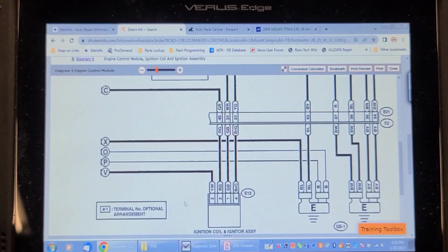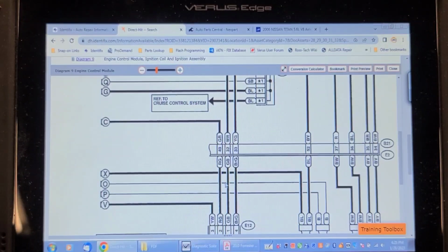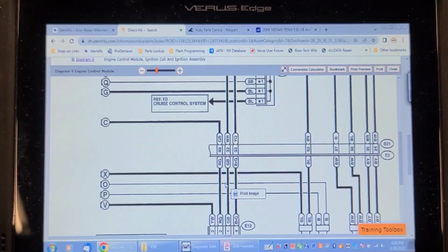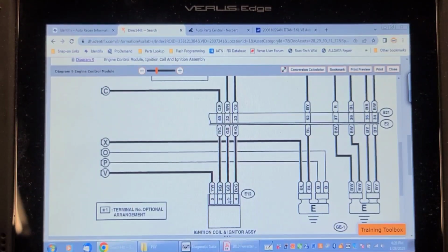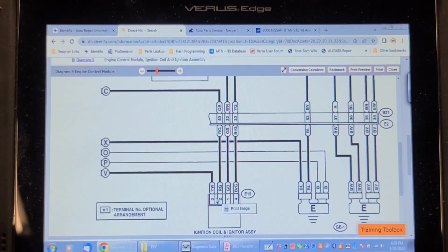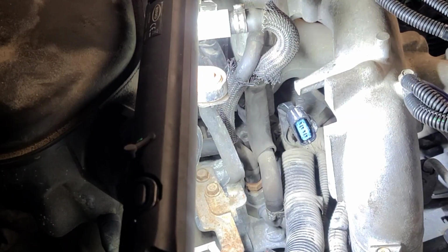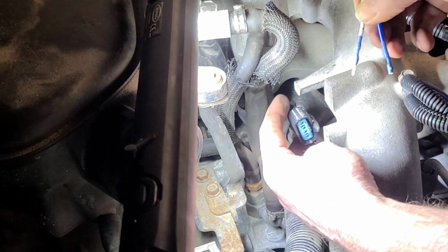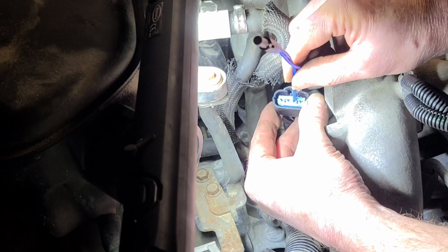I decided to take the coil off and put 4 jumper wires in across the coil, and check pin 1, which is the green wire. And I think I may have found something of concern when I was inserting the probes in there. Pins 2 and 3 are the power and ground. I'll show you what I mean. I was trying to put a T-harness in place, and I've got the proper size terminal here, and this one seems very loose. Both of these seem very loose.